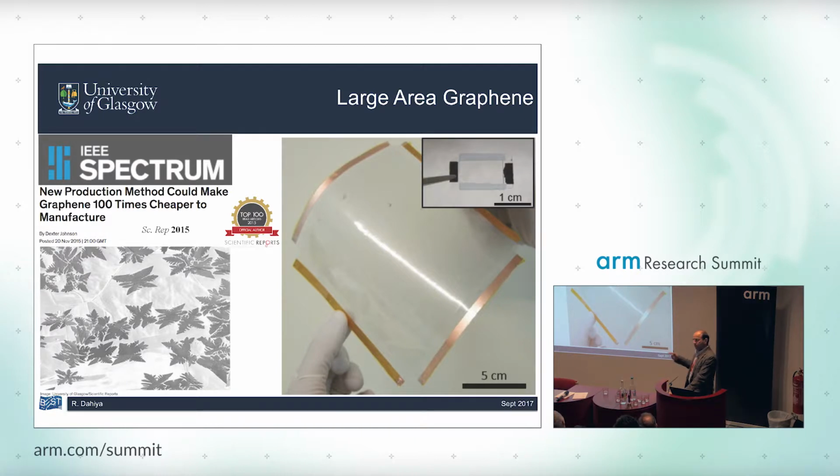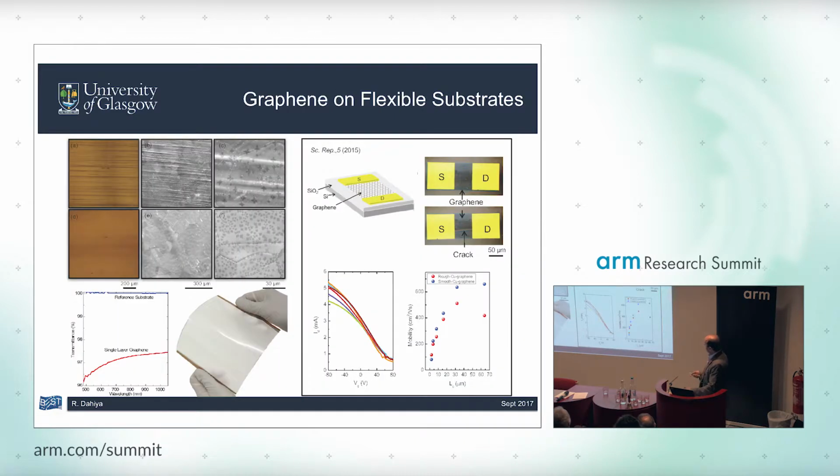Traditional capacitive sensors have a problem. So we also started looking into what other materials could be used, and printing started coming in at this point. We started looking into graphene, but graphene we know is normally available in small patches, though commercially also available in large area. So we synthesized graphene on copper and transferred it onto quite a large area, 25 centimeter by 25 centimeter, and the results were quite nice.